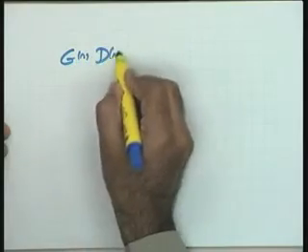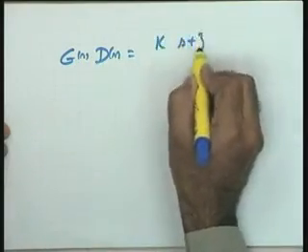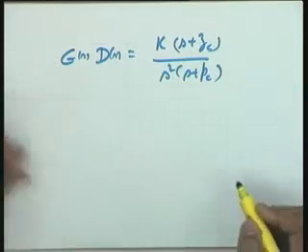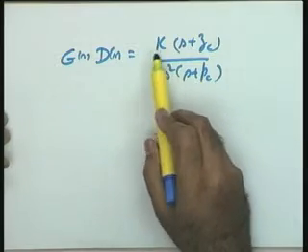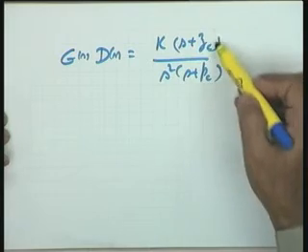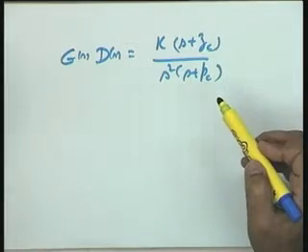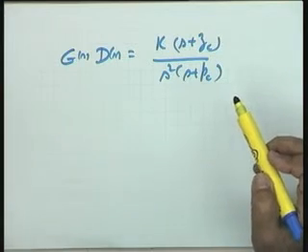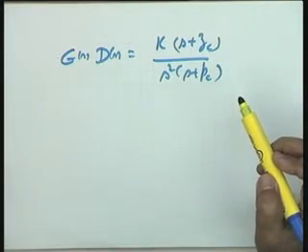So I think, if there is any point which comes to your mind as to how to take the decisions, please do tell me. In general you will find I have taken this to be GcS equal to K (S plus Zc) over S squared (S plus Pc). You find that the low frequency gain and the high frequency gain ratio is guided by Zc by Pc. That is why I said that Zc by Pc should preferably be of the order of 10 to give you a good filter design. This is the requirement based on the good filter design.